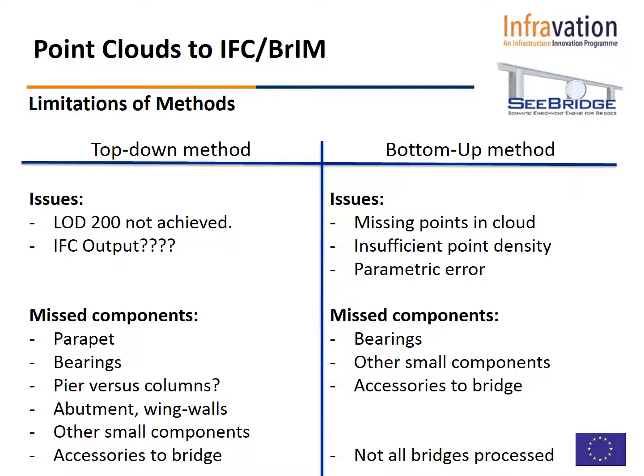The reason that one of the girders was 20% longer was because there was this set of points that appear to be phantom points. They don't really belong there. It's most likely a laser scan error or some kind of reflection. But these points lived beyond the extents of the actual girder and were considered part of the girder.